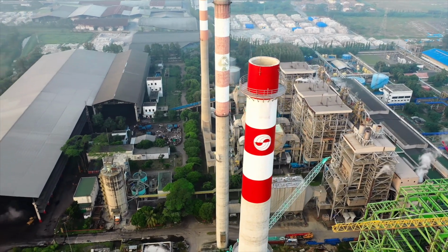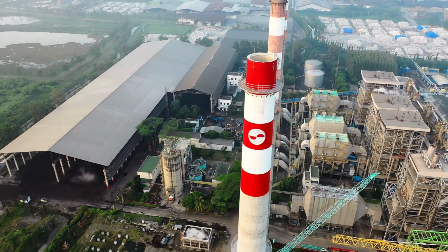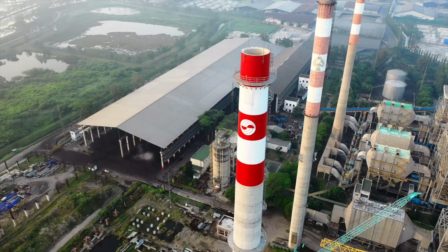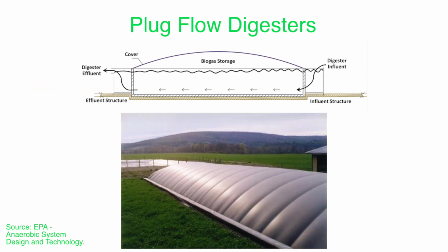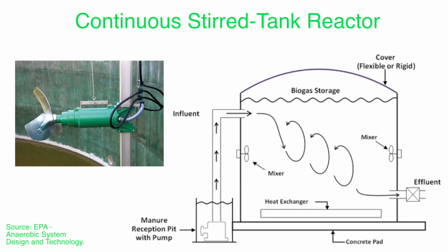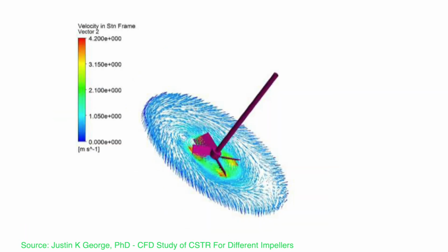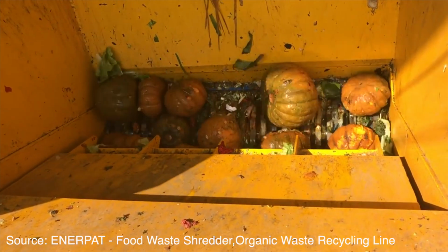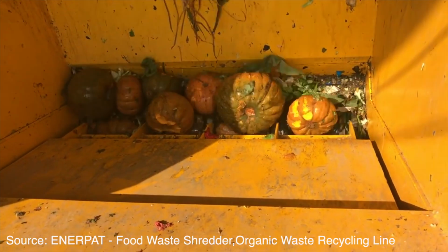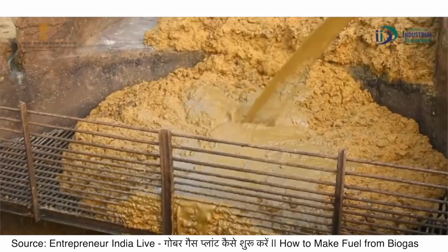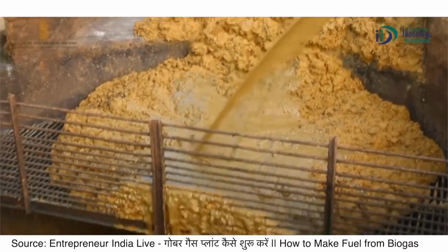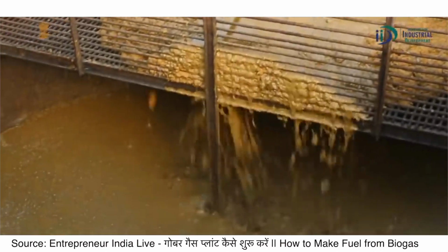In the biogas industry, there are different types of anaerobic digester designs, such as a covered lagoon, PFRs, and CSTRs. Compared to other configurations, the CSTR provides greater uniformity of system parameters, and thus is preferred. As the reaction occurs in the liquid phase, the biological waste must be processed into a sludge of approximately 90% water to be fed into the biodigester regardless of the type of feedstock.